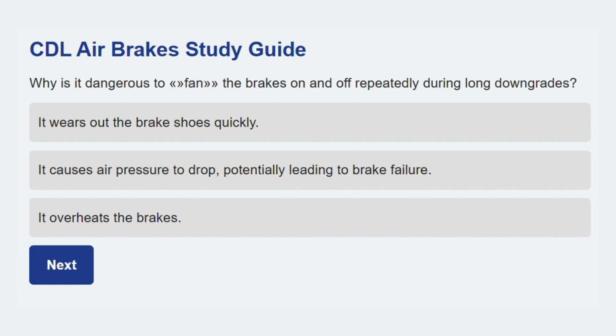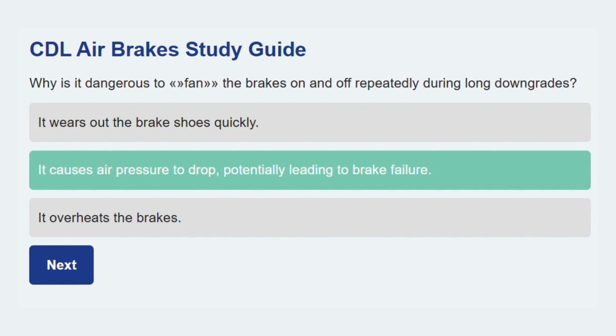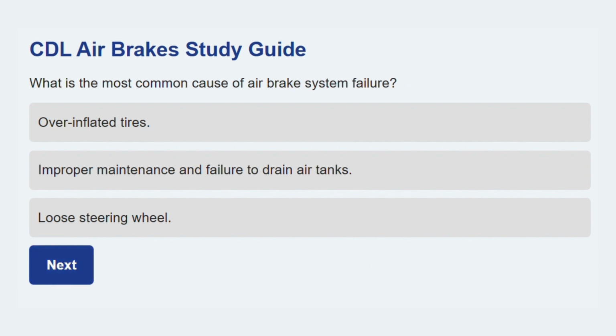Next on our list, why is it dangerous to fan the brakes on and off repeatedly during long downgrades? It causes air pressure to drop, potentially leading to brake failure. Fanning wastes air and can quickly deplete your air supply, leaving you without adequate braking power.